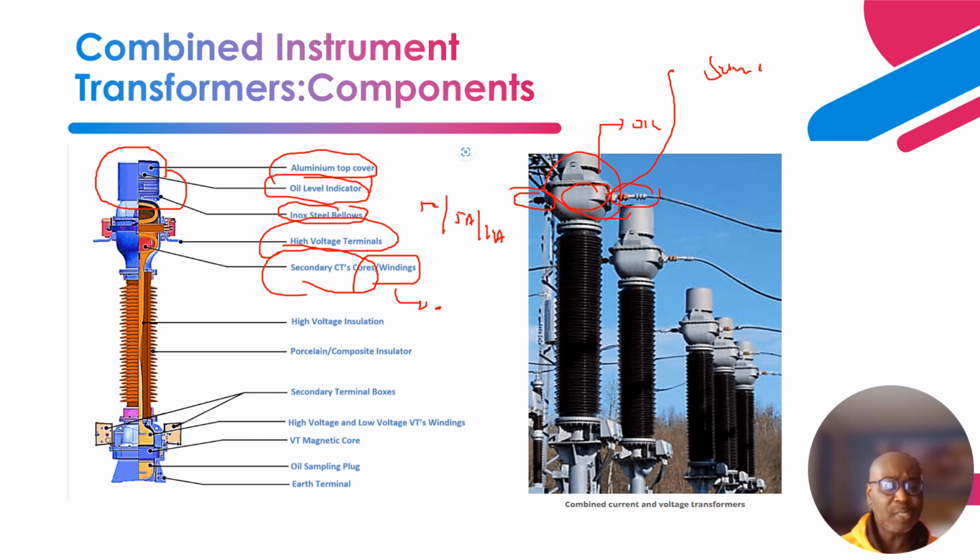Next is the high voltage insulation. Inside you have oil plus paper, and as I indicated, you sometimes utilize a combination of that to form graded capacitance, where the goal is to grade the electric field, so that you wouldn't have a high electric field that would degrade the internal components of the insulation system.